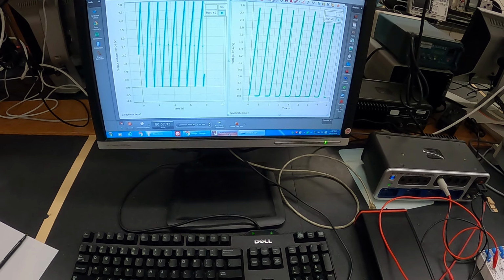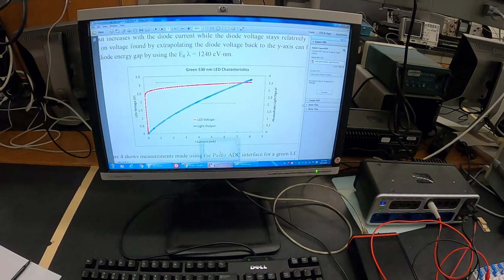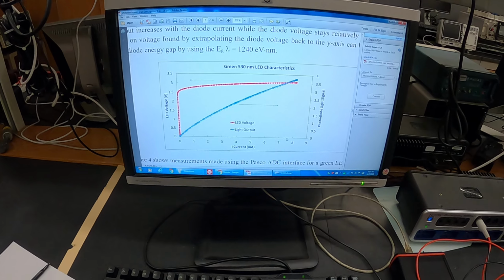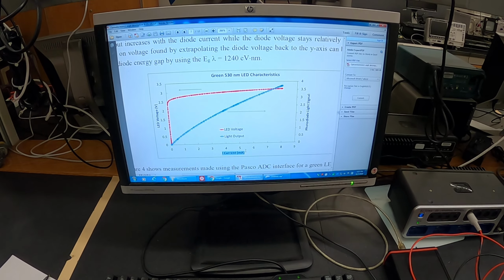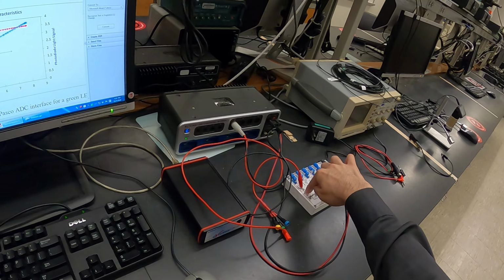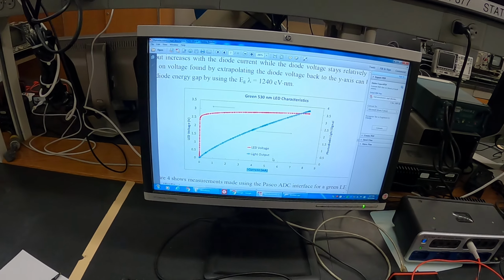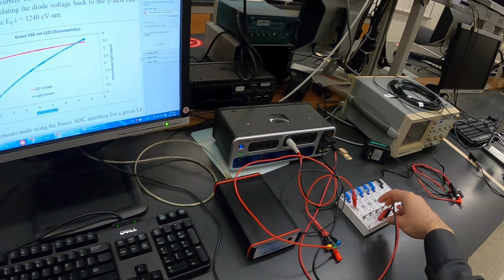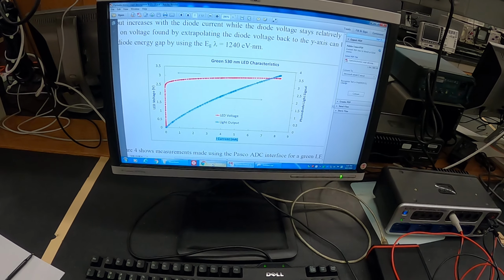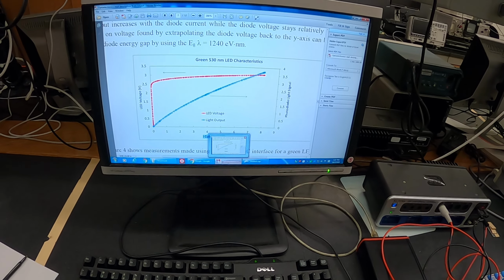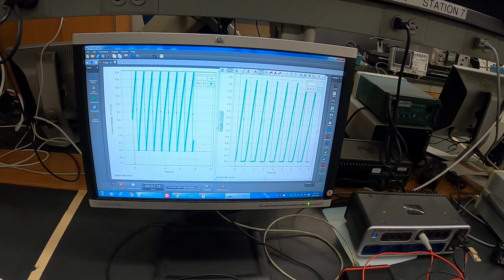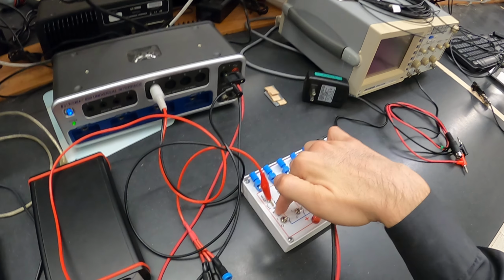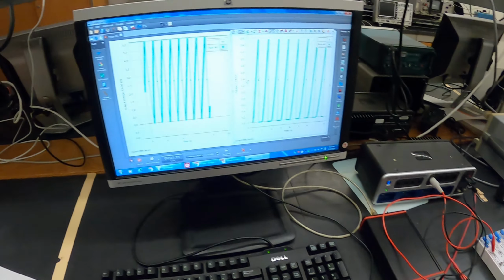So our first goal is to measure the activation voltage. In your lab, you see a graph like this, where we are measuring the current through this resistor here as a function of the voltage, or the input voltage. So I can convert the graph there to this graph here. I can convert the voltage to current if I divide by this resistance, which is 0.51 kilo ohm.